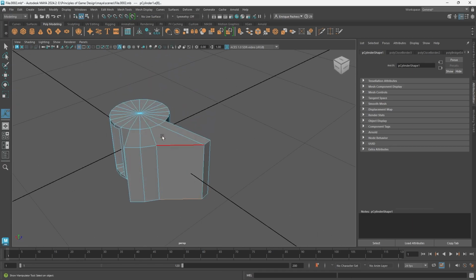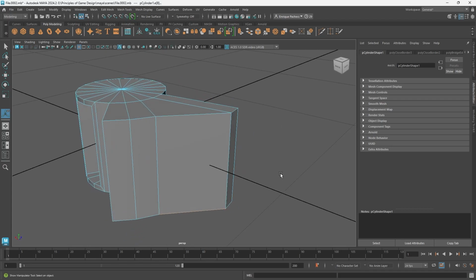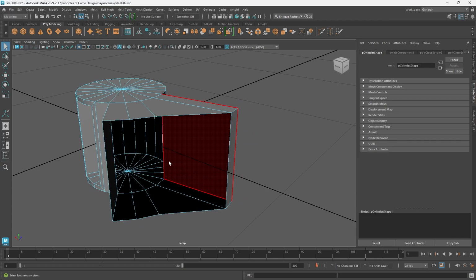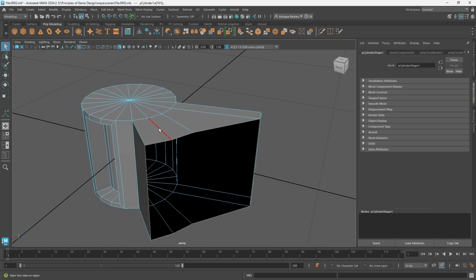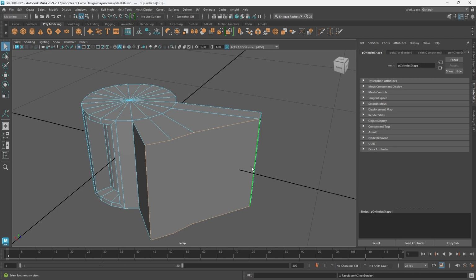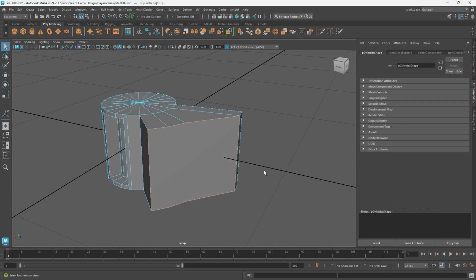And that allows me to create some interesting shapes. You can also use the bridge tool to correct multiple faces. So if I, let's say, delete these three faces next to each other, and I just want to close that hole, I can again double-click an edge, select the whole hole, and hit the bridge tool. However, if you do something like this, this face is now an n-gon.